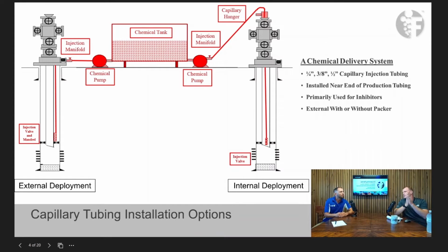Okay. And those clamps are there, what, just to protect that cap tubing? So the clamps go across your collar, which is going to be your biggest OD of your tubing. So you've got to protect that. You don't want to pinch off your tube, because you don't want that tubing banging against the ID of the casing, crushing that cap tubing.